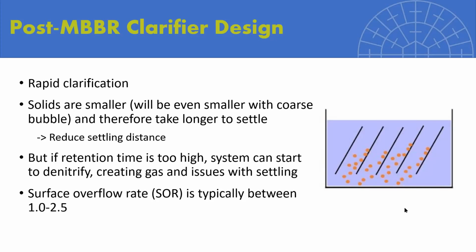So that's another reason to move to fine bubble aeration, is to increase the efficiency of your clarifier. Just keep in mind here that we typically design our clarifiers for a surface overflow rate between 1 and 2.5.